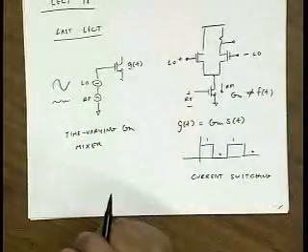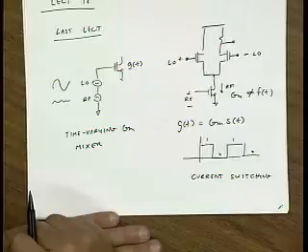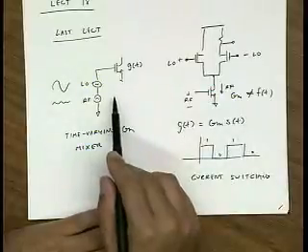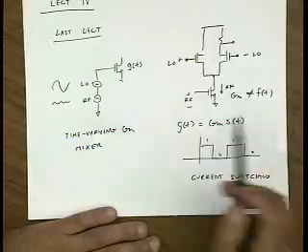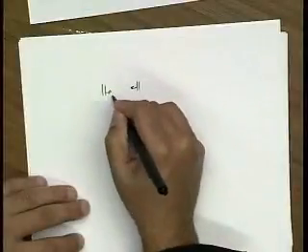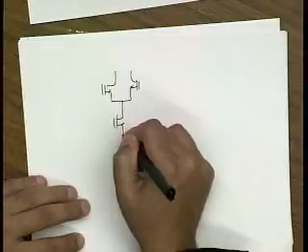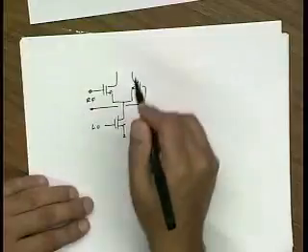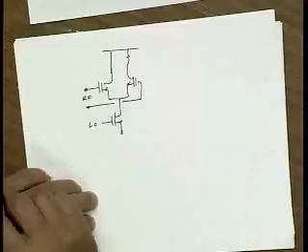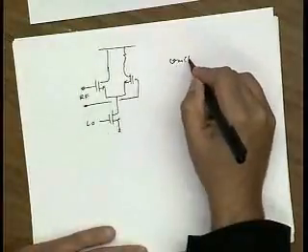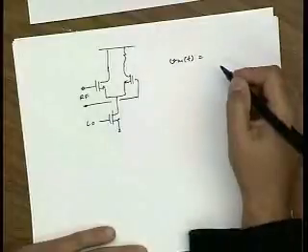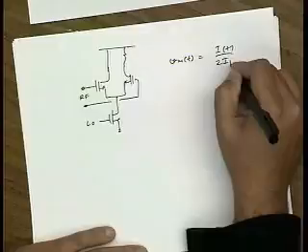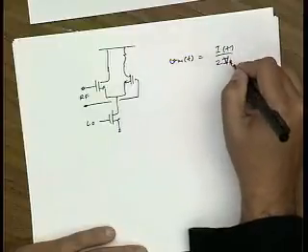Yeah, on the right side of the diagram, can you change the position of RF with LO? To the bottom tail? You can do that. Large signal at the bottom? Yeah. In which case, it won't be this kind of mixer, it'll be this class of mixer, right? Because then we're varying the bias current, which varies the GM. So let me just draw that circuit. Someone asked a similar question in office hours today. Is this a mixer? If I bring in my LO signal here and my RF signal here. And indeed, this is a mixer because what you're doing is the GM of this device is now a function of time because the I is a function of time. Whoops. So there should be I of t over Vt.